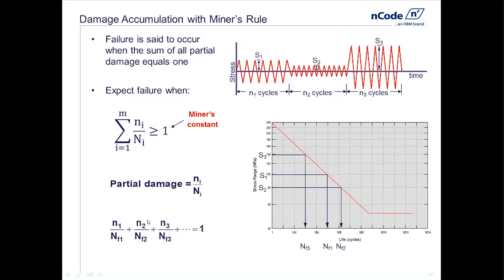If the total damage is equal to or greater than 1, that means we've used up the expenditures. We've completed our life. Fatigue failure occurred. If, on the other hand, as we hope, fatigue damage is a small number, that means we can continue to repeat this entire history. And that allows us then to say how many thousands of repeats or laps or hours or something to failure. This is Miner's rule in action.